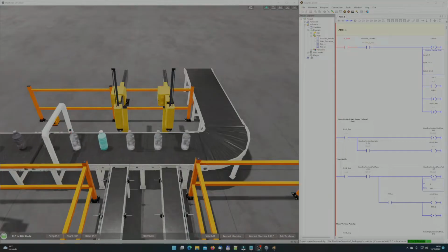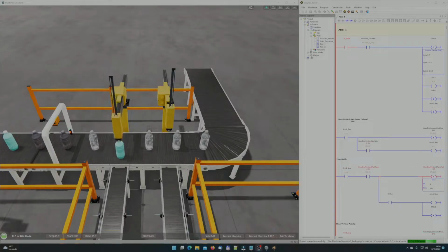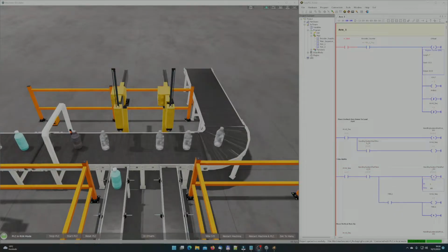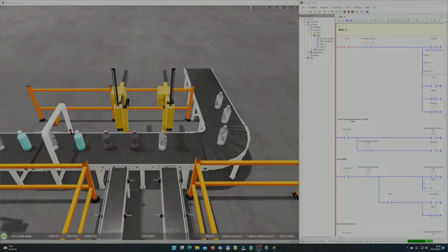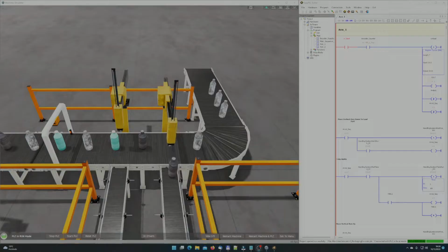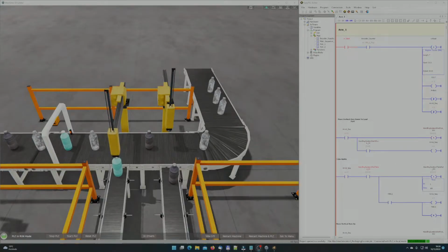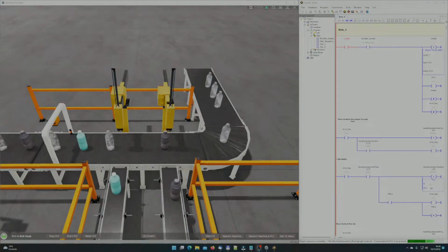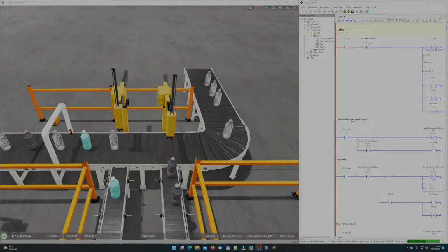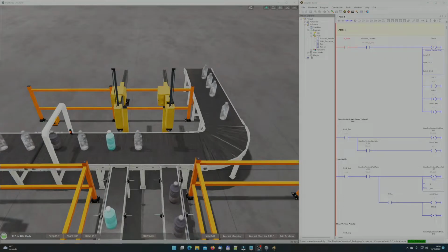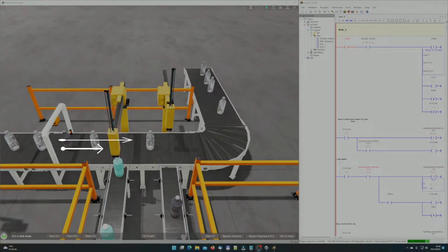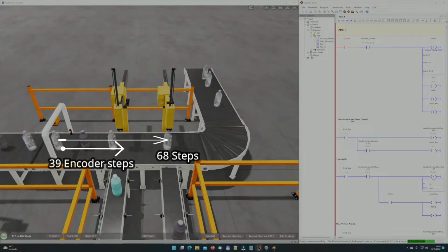The PLC will verify the value of the upper element of each one of the stacks. If this coincides with the value of the encoder, plus a specific offset belonging to the distance between the reading station and the output station, it means that there is a bottle in the right area to be evacuated, so the PLC will execute the bottle unloading routine, activating the corresponding robotic arm management signals. At that same moment the stack is adjusted, shifting each value and resetting the last one. The offset that indicates the distance between positions is initially calculated empirically, seeing how many encoder steps there are between the reading and output stations.